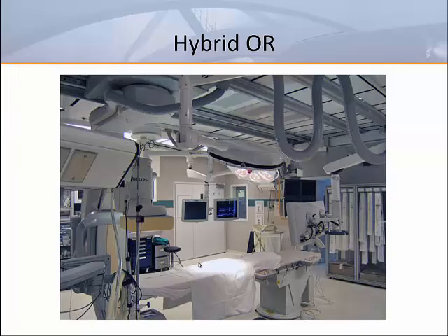Typical operating rooms are in the range of 550 to 700 square feet. Depending on the imaging modality and the equipment to be included in a hybrid room, these can be as large as 2,600 square feet. Ideally, a hybrid cardiovascular room will be between 1,000 and 1,200 square feet. Due to the size of the imaging equipment in an IMRI room, the size can range from 1,200 square feet up to 2,600 square feet.